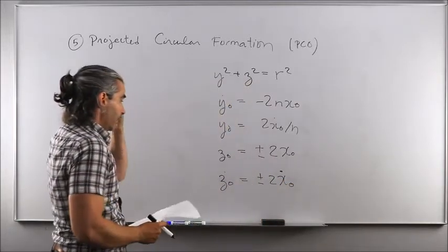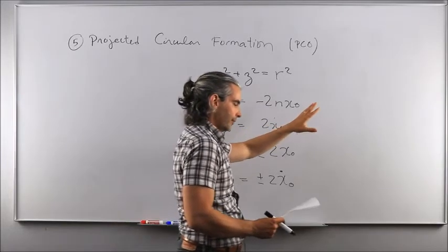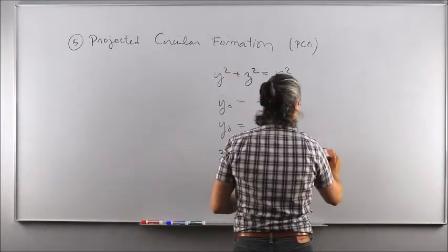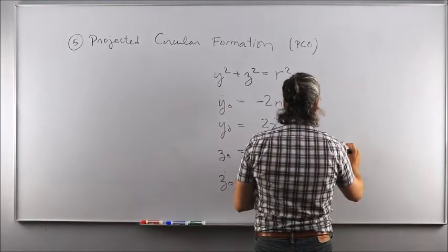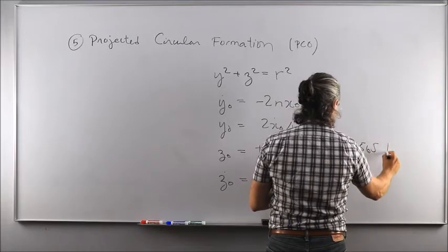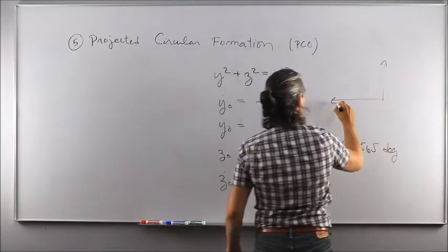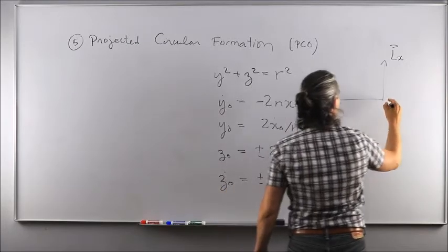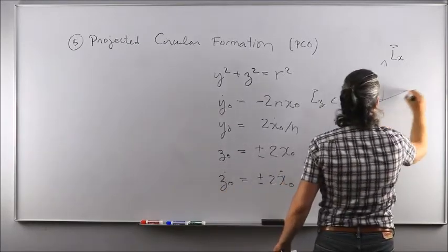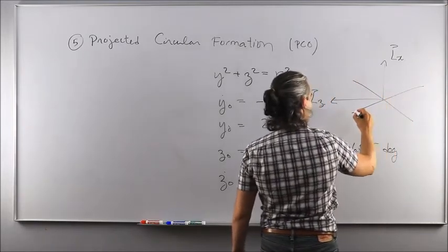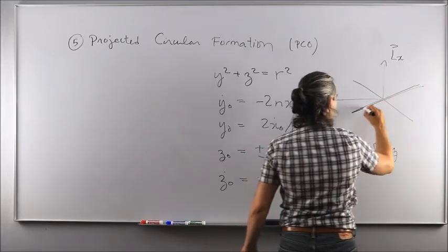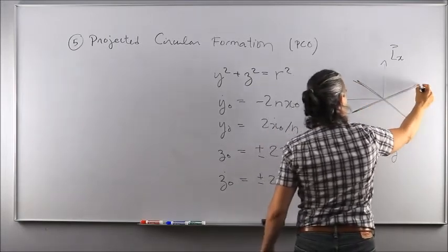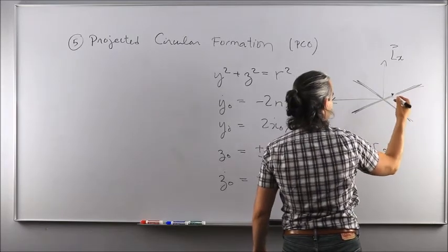Okay. Again, the plus minus corresponds to the plane in which the 3D ellipse takes place. So the plus here corresponds to a plane inclined at 26.565 degrees seen from the back. So this is your LX radially out. This is LZ normal to the plane, and LY is into the board. So now the plane in which the 3D motion takes place, in other words, the chaser spacecraft is limited to move along this plane or along this plane, 3D wise, and would draw an ellipse, okay, in this plane or in that plane.